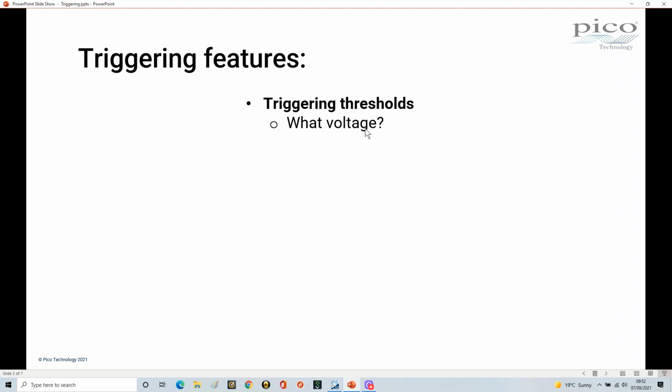And this is about analyzing and understanding signals. And this is why I say to you about using oscilloscopes, it's important to understand what you're looking for in order to set oscilloscopes up. And yes, I know there's auto features. If you've been watching other videos, you know I'm not overly keen on auto features because it doesn't educate you and you're not in control of your test equipment.